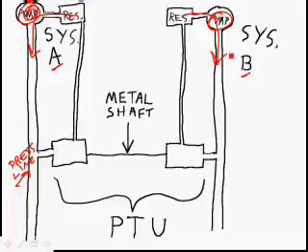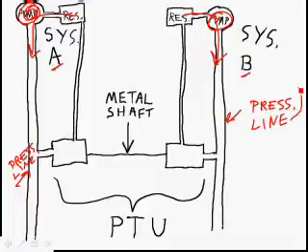It pulls fluid in from its reservoir, and here's the pressure line in system B. So we're flying along, and the pump quits. If the pump quits, then the pressure inside the pressure line is going to go down. What you can do is flip a switch in the cockpit. It opens a valve, and it allows the pressurized fluid to go into this device right here, and this is